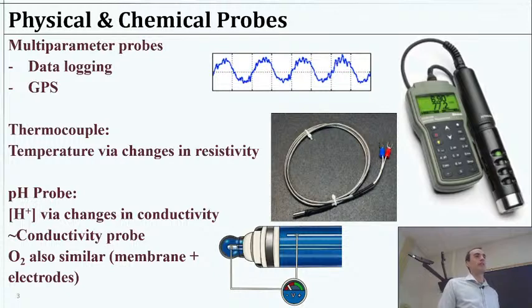Lots of total dissolved solids. So that's the proper maintenance for a pH probe. It requires some dirtier water rather than cleaner water. Of course, you're probably going to want to rinse it off before if you need to sample something else and you don't want to contaminate that sample, but a quick rinse with DI and storage in saline is fine. Storage in DI water is going to strip it all out, and that's bad news.